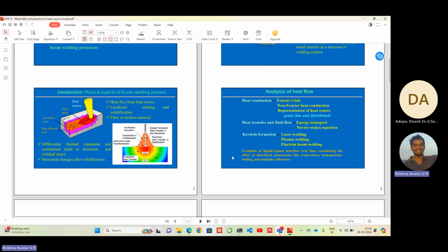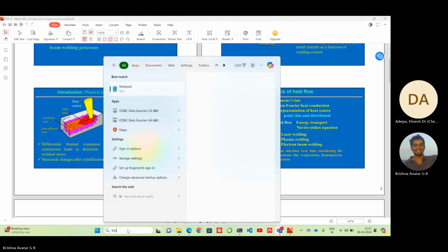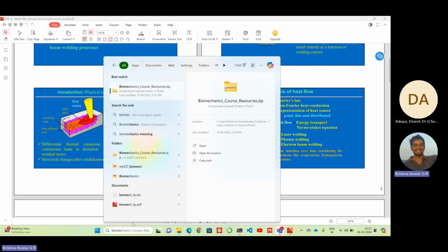So one example is when you cut an onion. Say you want to cut it such that you make some circular discs out of it. You cut it laterally, so you get plates after plates. Now if you take one ring of the onion, the moment you cut it, the ring will just open. That is because of residual stress.